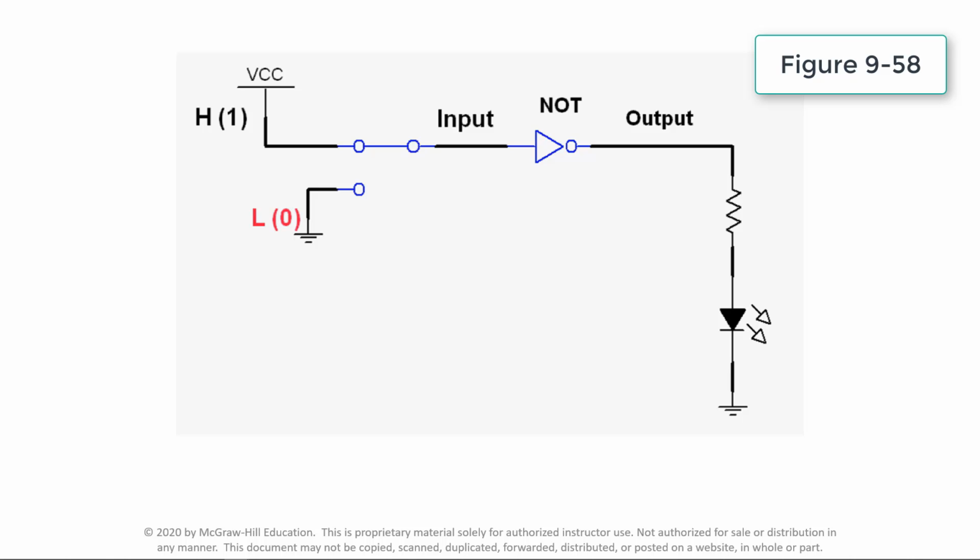One hardwired device equivalent to this circuit would be a normally closed, held open door switch. When the door is closed, the switch is open. When the door is open, the switch is closed.